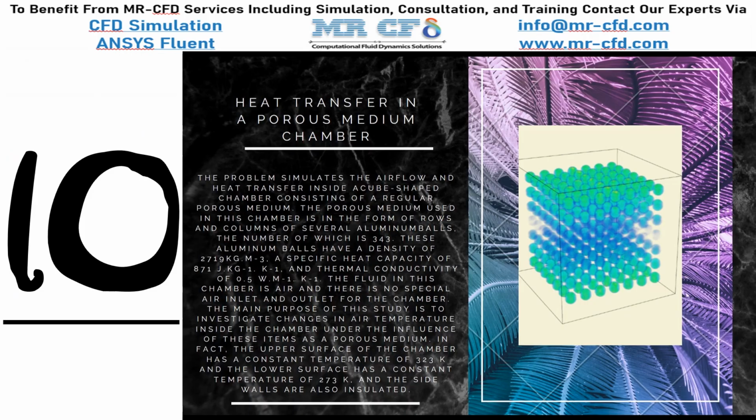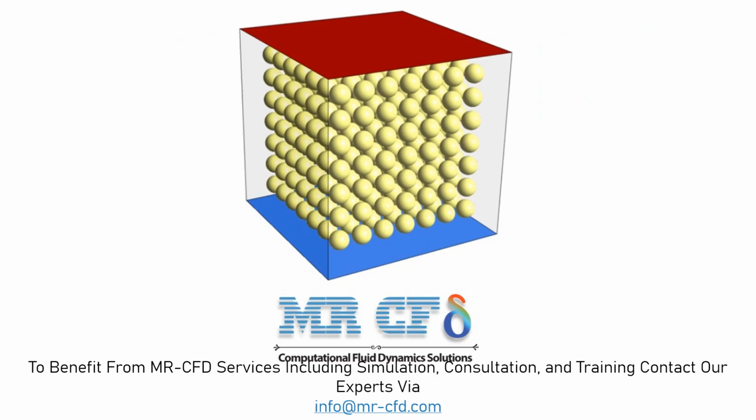Finally, a summary of different settings and setup that we have used in our project is presented to you in the slide. In this project, we will simulate the air heat transfer in a porous medium chamber. The present model is three-dimensional and is drawn using Design Modeler software. The present model is related to the chamber, which has several spheres as a porous medium in three different directions. The total number of these spheres is 343.